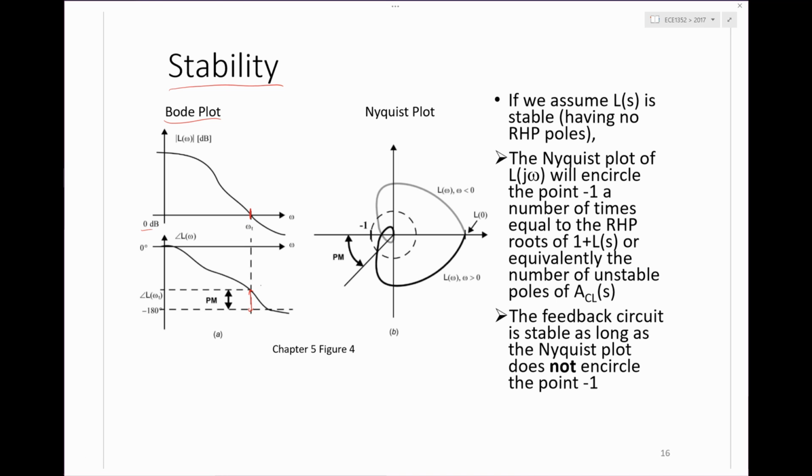So we're not going to do any of those types of circuits in the course, as I said, but I just want to take the opportunity before we go into the simpler first and second order feedback systems to remind ourselves of the underlying Nyquist criterion. Basically, when you have a complex function like L, you draw this contour in the complex plane, which is drawn to encircle the entire right half plane.